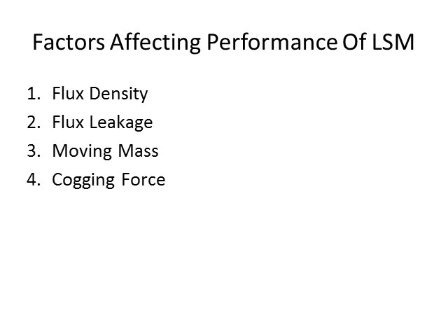The third, the moving mass, refers to the moving components of the motor, and lower mass is preferable in most cases to produce a higher acceleration. The fourth, the cogging force or detent force, is present in a linear motor due to the presence of iron and is basically the attraction of iron to any permanent magnets in the motor, resulting in a cyclical force ripple over the travel distance. It's undesirable and reduces efficiency.